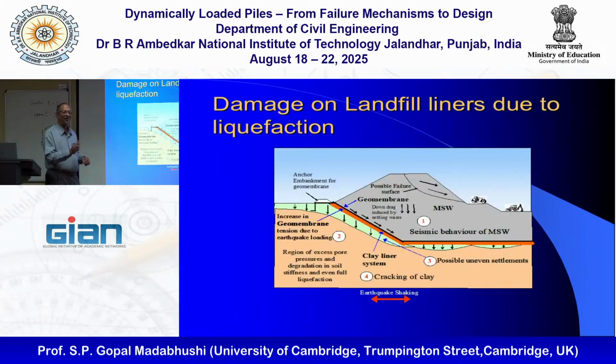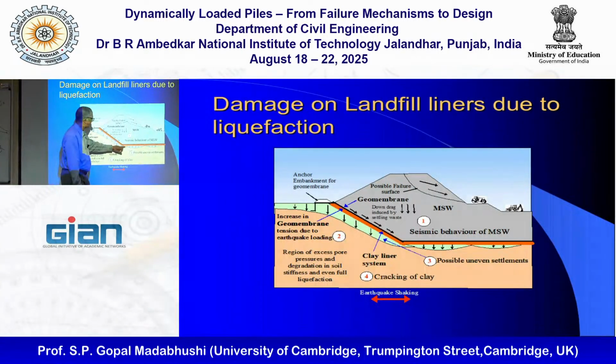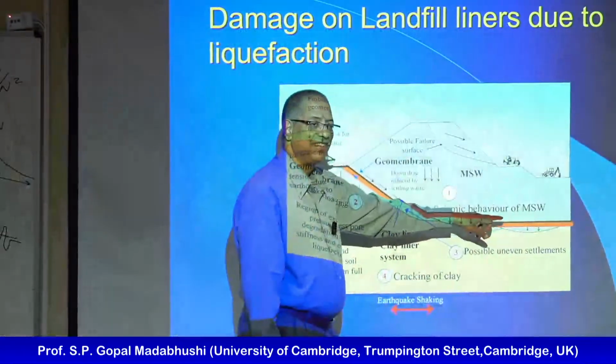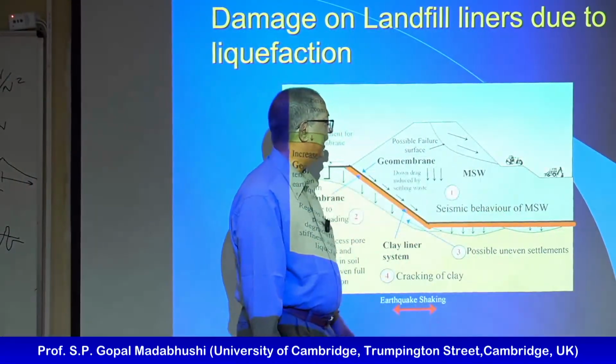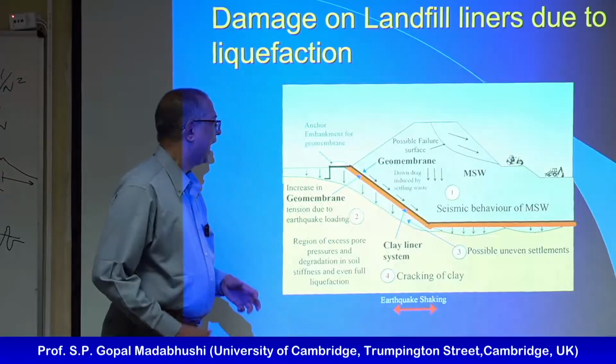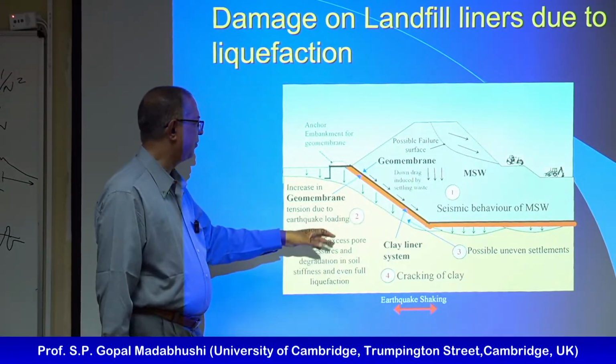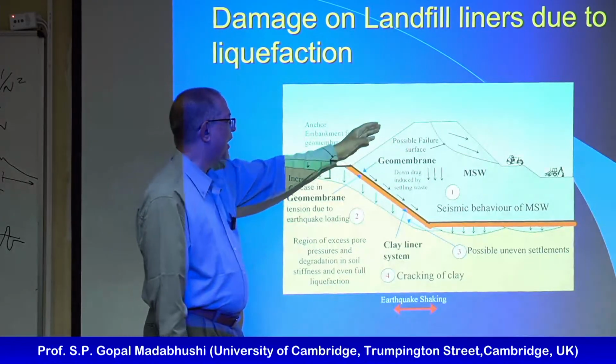We tried so outside Delhi and elsewhere. A real properly designed landfill should have a clay layer, a geomembrane, base layer, a geomembrane, and it goes onto the other side as well, right? And after the waste is filled, you also have to put a top cover.